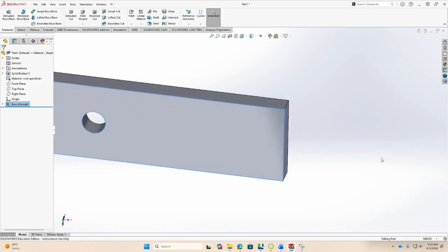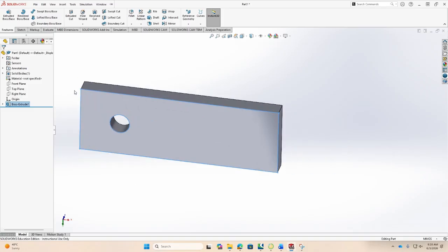Again, now I have several options to take things from here. A more detailed analysis at this stage will separately model the pin, right, and then create an assembly, right? But for many practical analyses, we don't really need that level of detail. Actually, using that level of detail can even cause more confusion in the design, because then you will have to answer questions like how accurately I am modeling the contact conditions between them, right? Because then you have to define what kind of friction is there, what kind of surface is there. So all of those things will then affect.